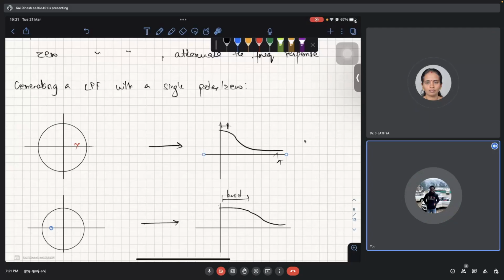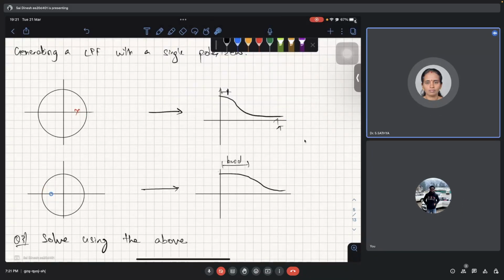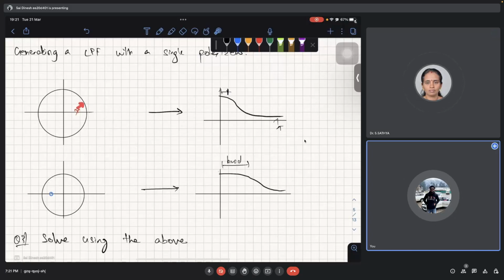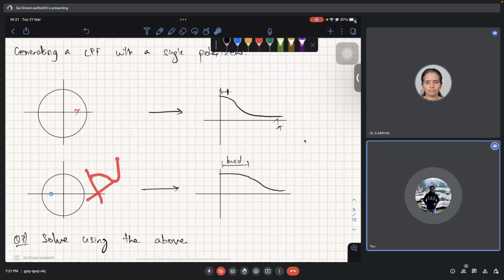Then why do we care about all other values of z? Now it is evident that the locations of poles and zeros are actually important. Here, the pole is getting to unit magnitude, so the peak is actually going to infinity, and when a zero is going to unit magnitude, the particular valley is going to 0, right?